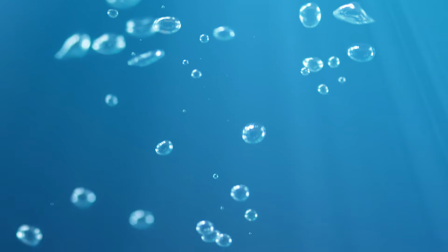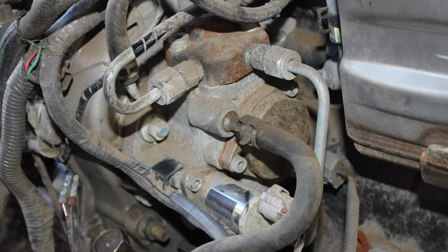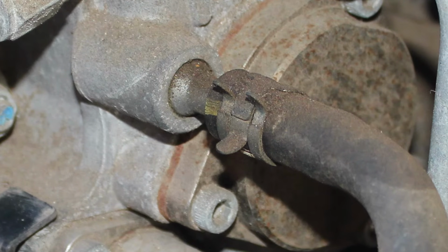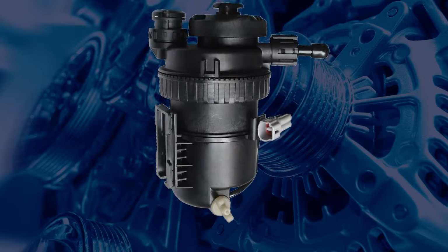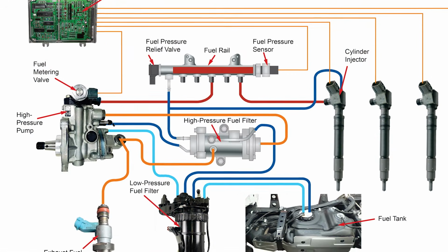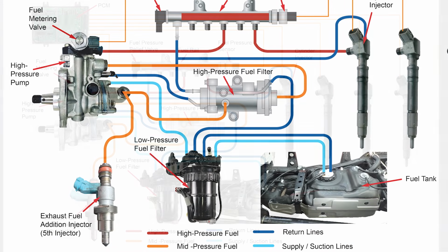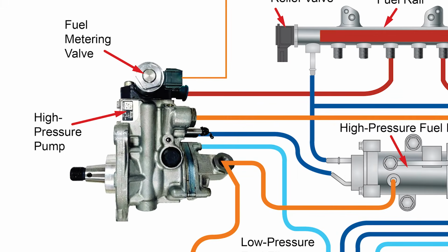Air being sucked into the fuel lines is a common cause of this code for engines that draw fuel from the fuel tank via a lift pump. Some commonly overlooked air entry points are loose spring hose clamps, poorly fitted fuel filters, and perished or damaged water drain O-rings. However, there are many other possible faults in the fuel system and return lines that can trigger this fault. There are also many possible mechanical problems in the engine that can trigger P0089.